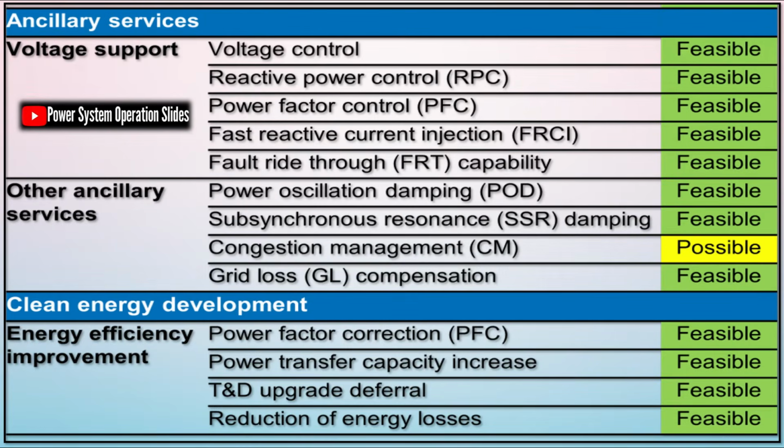Power quality is another area where these devices prove indispensable. Wind turbines equipped with power electronics can introduce harmonics and flicker into the grid, degrading power quality. Grid operators enforce strict limits on these disturbances. STATCOMs and SVCs mitigate such issues by smoothing reactive power flow, reducing voltage flicker, and improving the overall quality of electricity delivered from the wind farm.